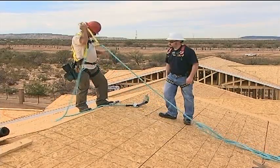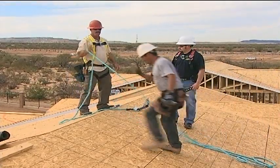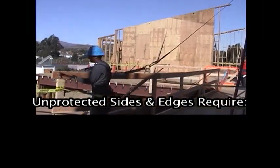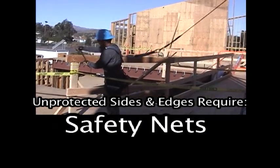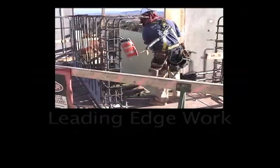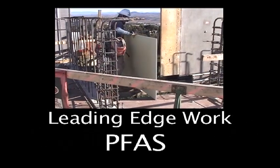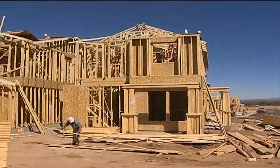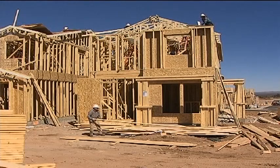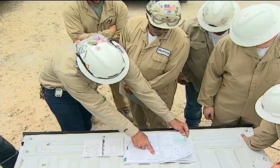Areas and/or activities where fall protection is needed and the type of protection required includes, but is not limited to, unprotected sides and edges require the use of guardrail, safety net, or a personal fall arrest system, PFAS. Leading edge work requires the use of guardrail, safety net, or PFAS. When it is infeasible to use fall protection or it creates a greater hazard to use these systems, an employer may develop and implement a fall protection plan.